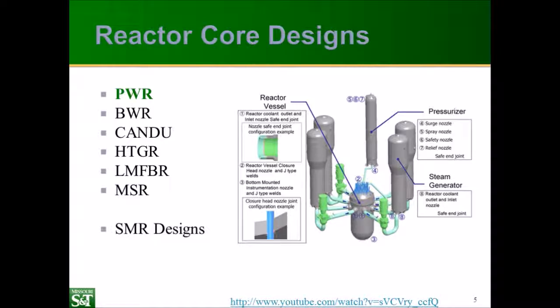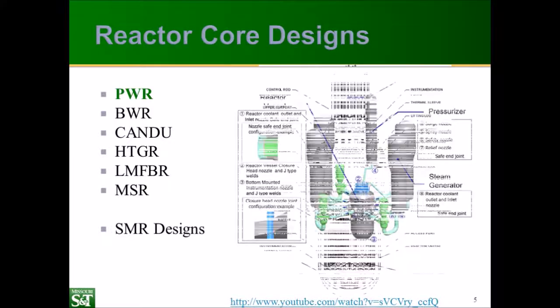Here, we're looking at the heat transfer in the pressurizer, the boiling and condensation behavior that is used to maintain pressure in the system. And we're also looking at heat transfer through the steam generator. So you have convection on both sides. You're going to have boiling on the secondary side, and then you have conduction through the steam generator tubes. You also have a number of safety features: emergency core cooling to inject cold water, suppression pool to help condense steam and reduce pressure, and things of that nature.